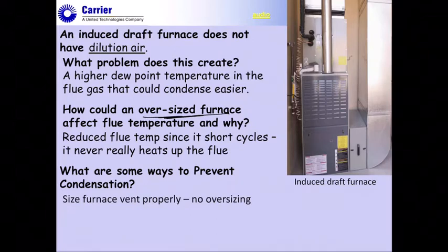What are some of the ways to prevent condensation? The first thing I would say is size your furnace and vent system properly. You don't want to oversize that. You don't even want to oversize the furnace if you can help it. So the sizing and the load calc are going to be really critical, making sure your firing rate is appropriate. So check and adjust that firing rate.